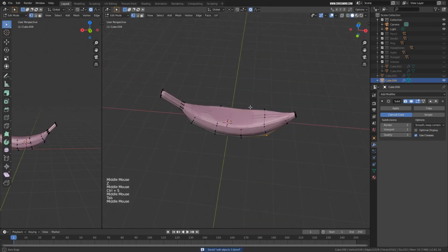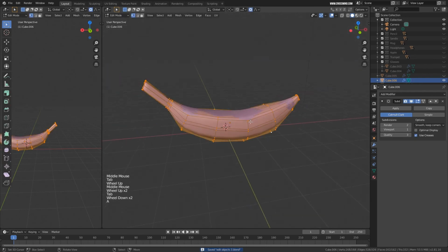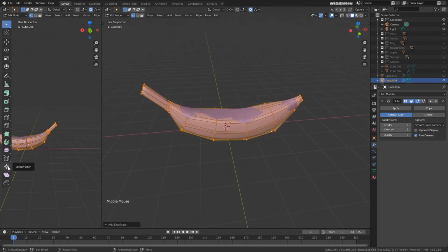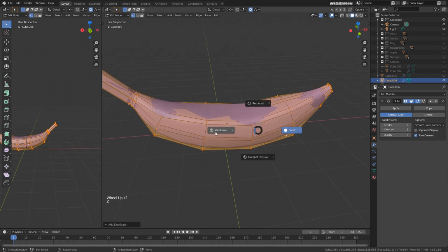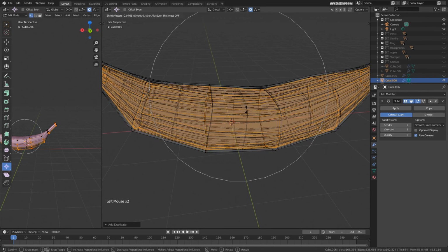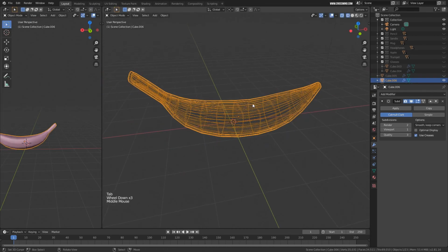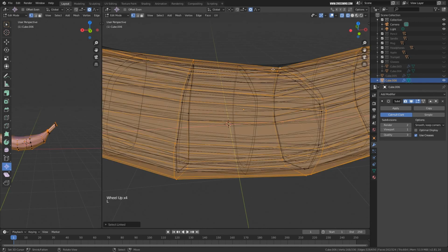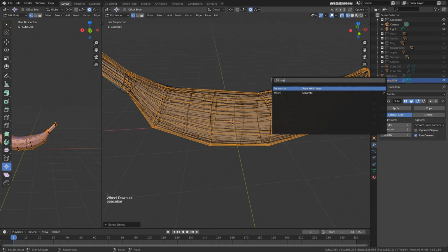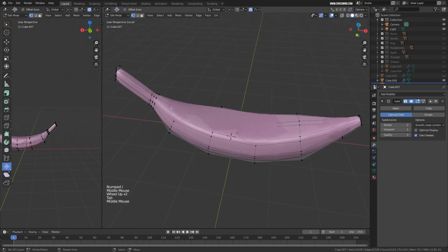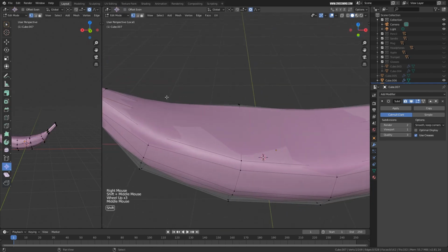And what we'll do is we'll select all the faces and press Shift D and create a duplicate out of this. And now I'll go into wireframe mode, shrink and flatten it a bit to make the inside of the banana. Now I'll separate this entire outer object. I'll bring my mouse on the outer edge and press L, and the entire object is selected, and separate this one by selection. Yeah, I'll isolate this one, and I'll see if I can peel this off maybe.